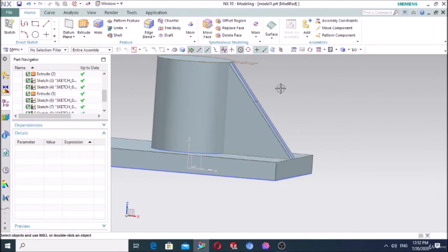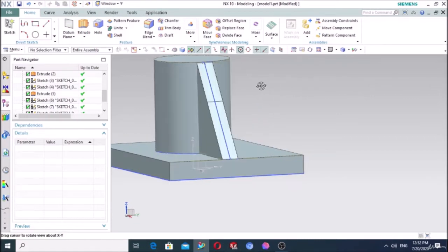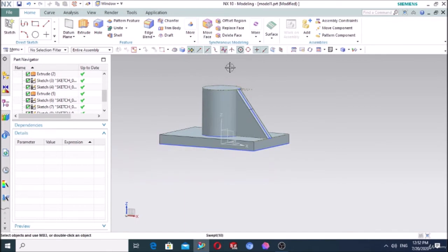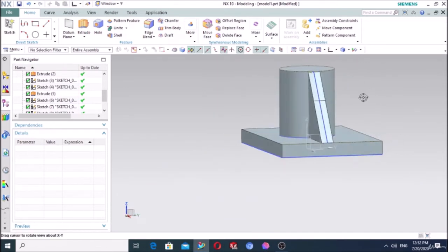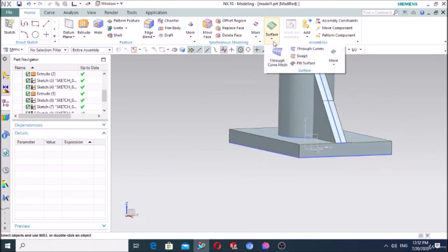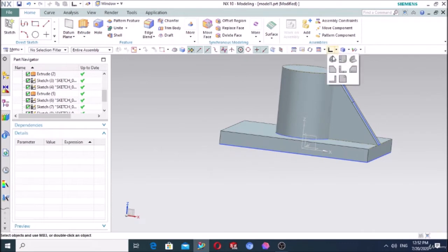With the traditional way as with the previous rectangle, it's not possible to obtain the rib from edge to edge. So this is the way of obtaining the rib in the cylinder case with the swept command. In upcoming lessons we will learn deeply about the swept function to obtain some complex surface elements.